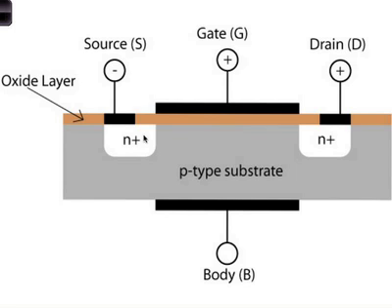Now, last class we talked about capacitance, but the capacitance we're talking about is in this direction. So keep that picture in mind. It's a little bit confusing. The current is, of course, flowing from left to right. The capacitance that we have been talking about, and will talk about today, is the gate oxide capacitance, which means that, recall, no current can flow here, right? This is an insulator, but this is a capacitance. We showed that this is more or less like a parallel plate capacitance. You have a metal here, a dielectric oxide here, and then a pseudo-conductor, an inversion layer and all that. So it's a little more complicated than a parallel plate capacitance, but that's the capacitance we're thinking about here.